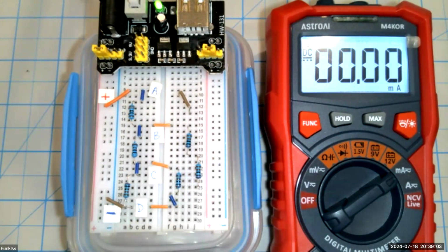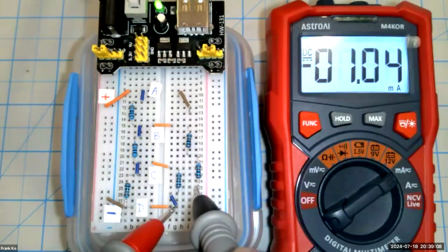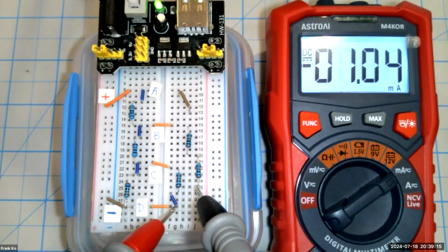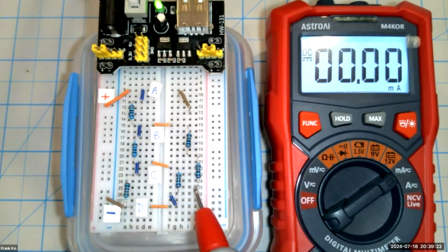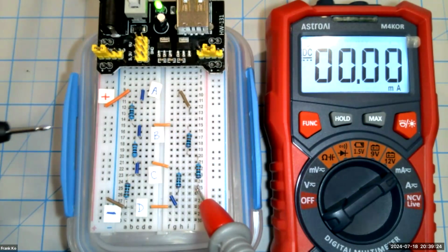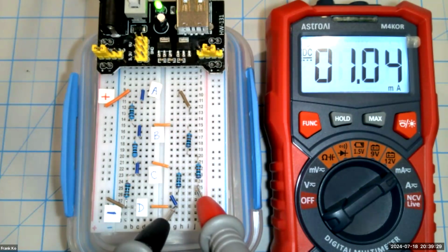Now, suppose you do something and then you switch it around and you say, hey, I've got a negative 1.04 milliamp. What gives? Where's this negative current coming from? Well, that's because you have your ammeter probes reversed. The red probe must be on the more positive side of the circuit, which is here, and the black probe must be on the more negative side of the open, which is here. And so here we show the 1.04 without the negative symbol. So we were able to verify the current flowing through load number 5.